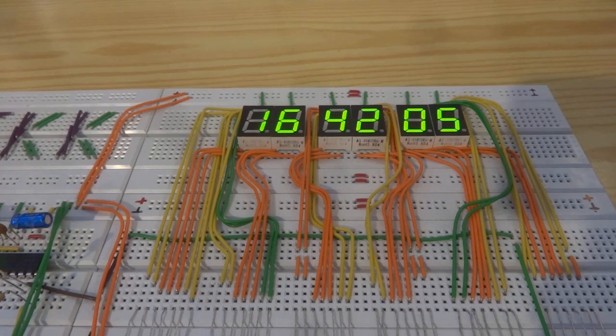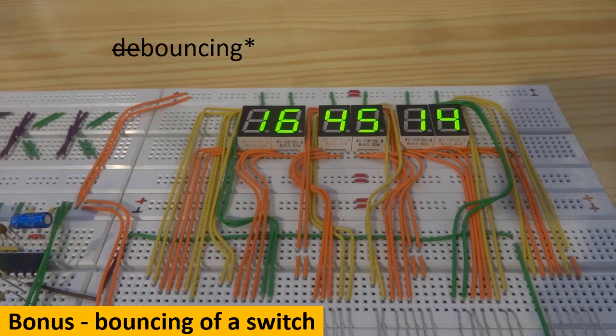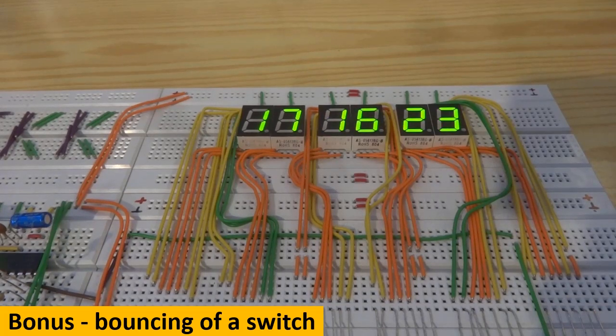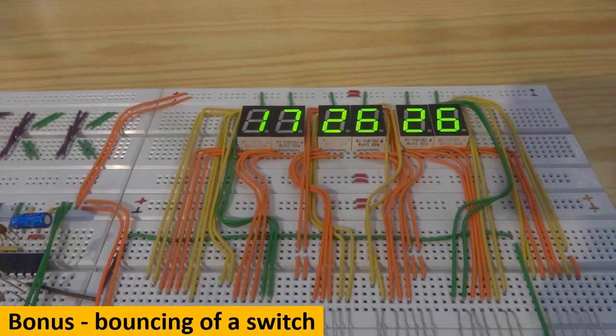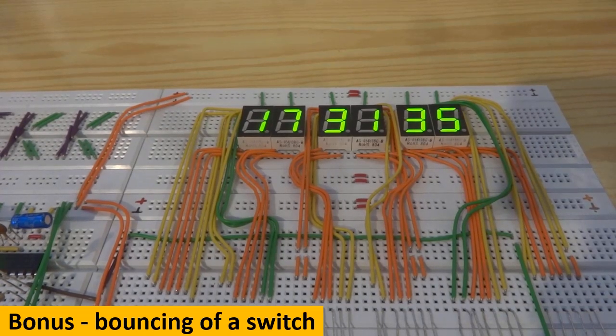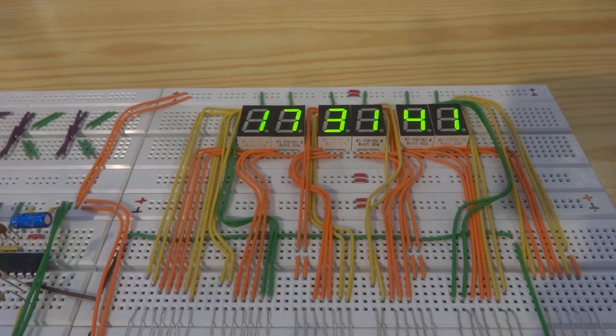Sometimes when pressing a switch, we have problems with multiple changes of state, which is due to bouncing of a switch. Oh, you can see here multiple changes of state during one press, but switch bounces and changes the state high and low multiple times. I'll show you how to reduce that effect in a couple of minutes.